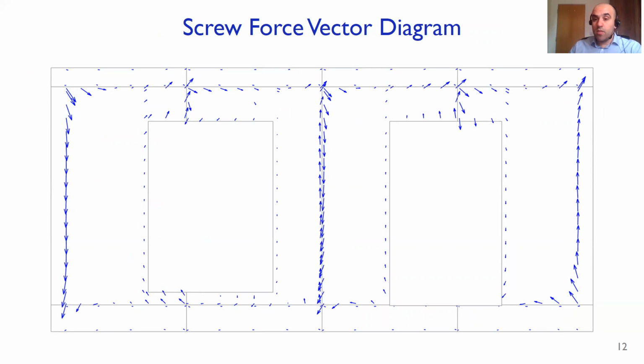Monitoring UEL output is very important in getting the simulation right, especially if the UEL spring results have significant influence on final results, as indeed is the case in cold form steel framed shear walls.